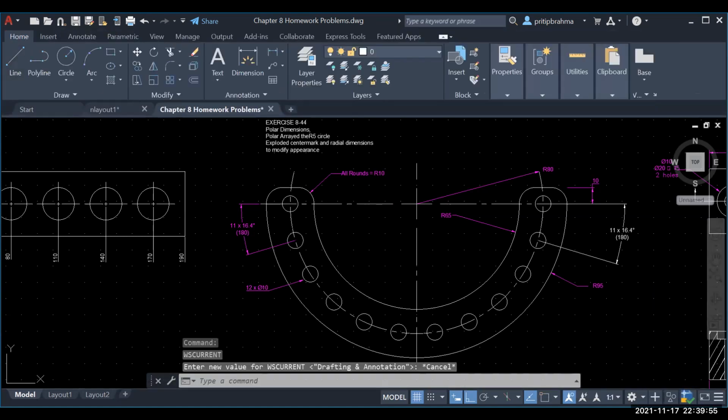We should add a symmetry symbol right here so that that is perfectly clear. And a symmetry symbol is basically 2 lines, and I should center them, but it's 2 lines that are like this on both sides of the center mark here.